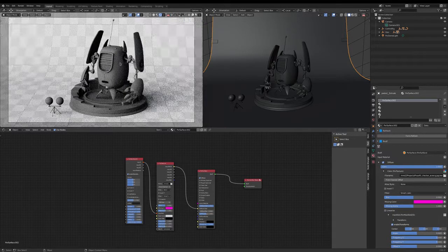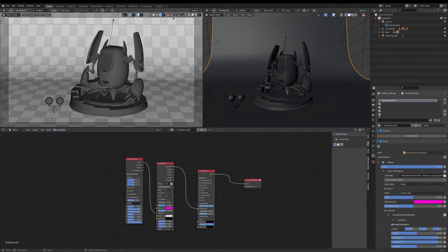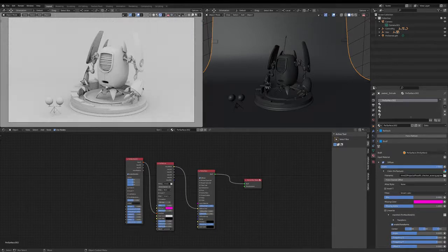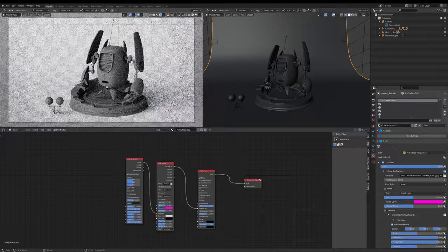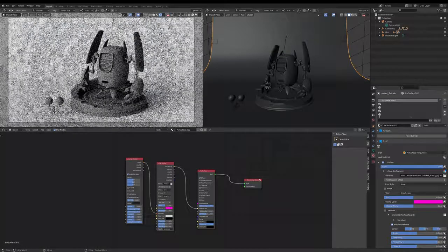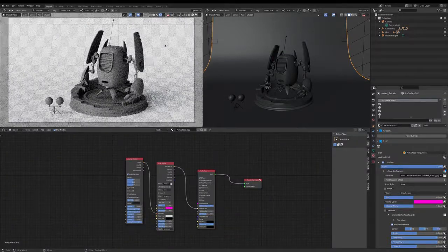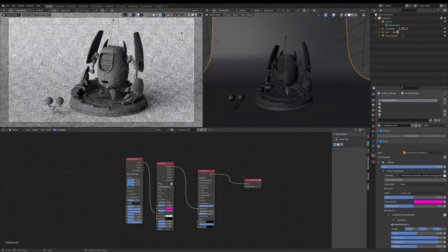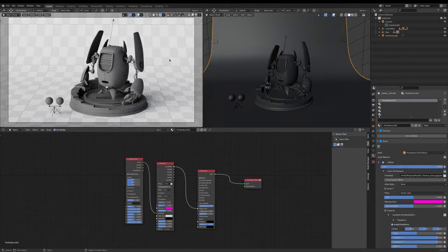So you can change it to see what the direct lighting is doing. You can change it to this default mode, which is also quite useful for debugging. And then you've got this ambient occlusion integrator. This Pixar Unified is what Pixar in the studio actually use, but we don't necessarily recommend it because it's pretty render intensive. So the next one here you have is Pixar VCM, which is really great for things like glass and caustics. But like I say, for most cases, you really just only want to keep it on this path tracer.